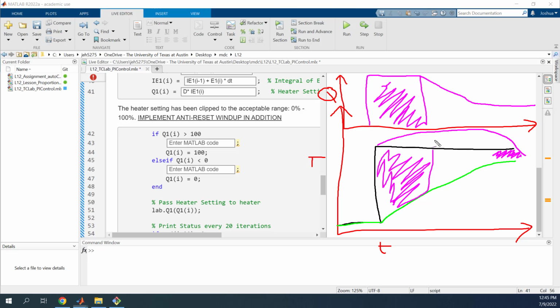And then we're going to have some oscillation as it has to overshoot and then undershoot the set point before hopefully it finally settles out. So that's kind of the downside of PI controllers in a nutshell, and hopefully that rambling makes sense, but I think it's something good to go over.